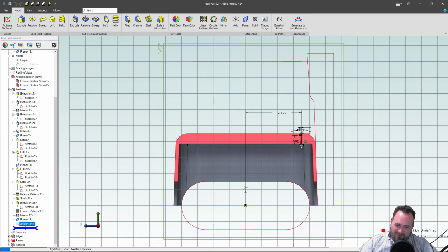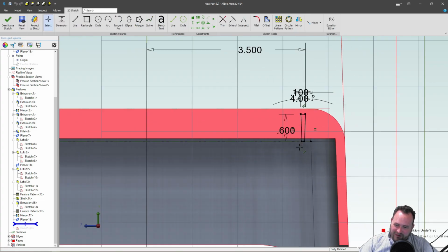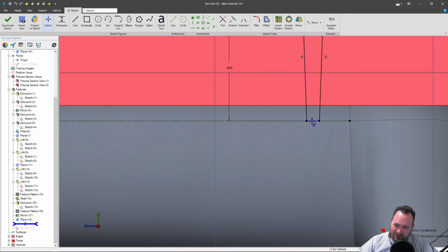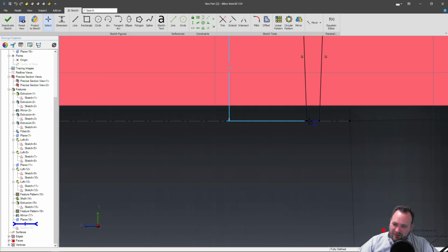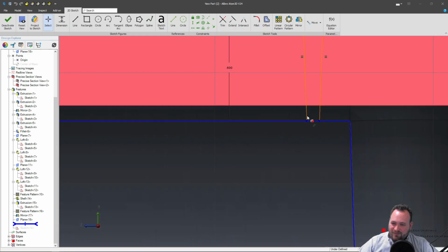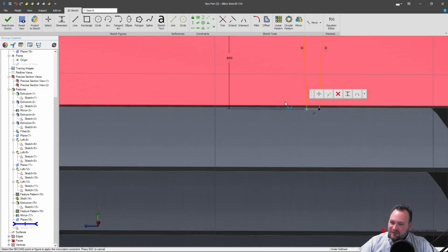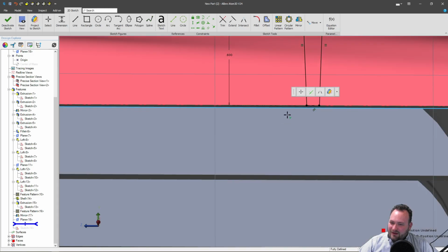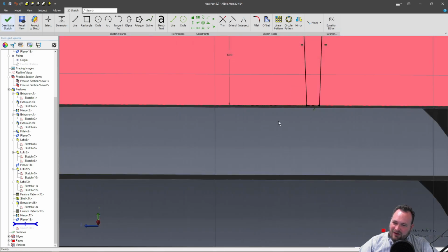Of course, that's what I get for going into that view. So we've got to get rid of a coincident on there. I guess this is a reasonable example of editing a sketch. Hopefully someone watching might need that. So where is my coincident? I'll just delete my imported line. Yeah. We're going to say coincident from this point onto that edge. That's better. Okay, now it's making the point that I want it to make.